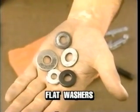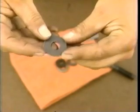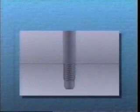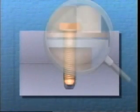Flat washers distribute the bolt load over a larger surface area. Be aware that flat washers have round and sharp-edged sides to them. The rounded side must face the bolt head. Installing a flat washer wrong causes the edge of the washer to gouge the bolt head, creating a weak spot. Under stress, this weak spot can cause the bolt head to break off.